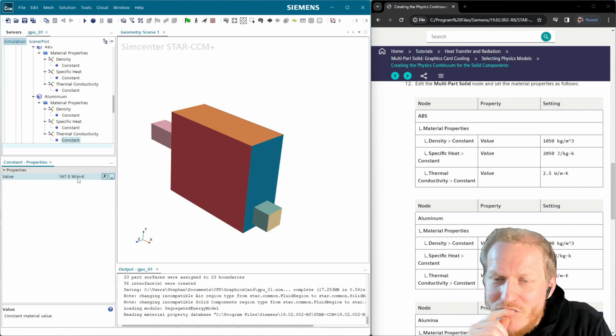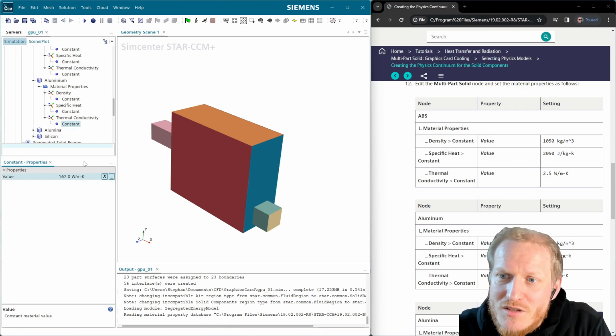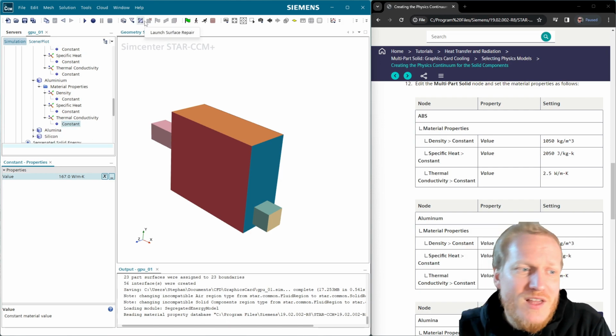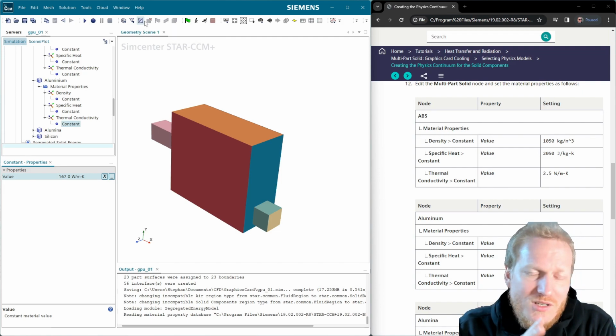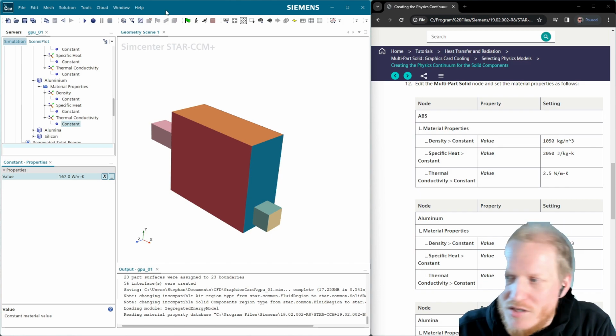It's a different thermal conductivity for aluminum, because the original one is only valid for extremely pure aluminum. And once you put a single bit of alloy into that, your conductivity instantly goes down by 20%.